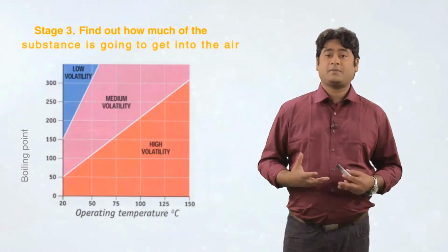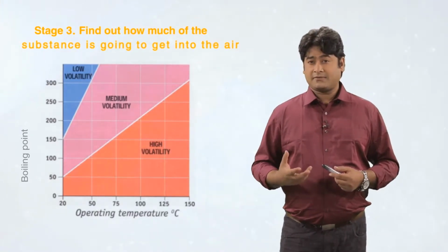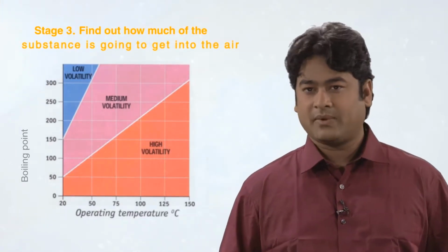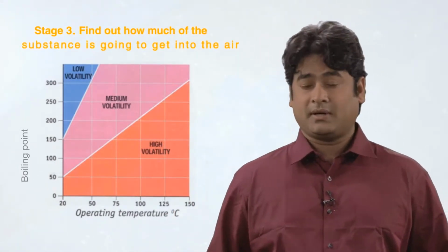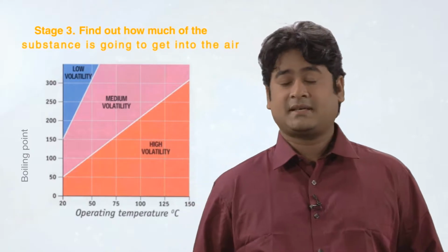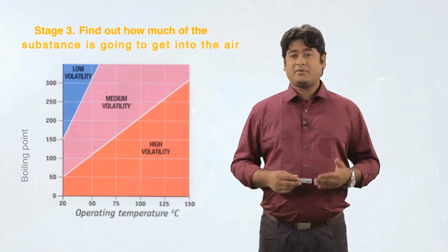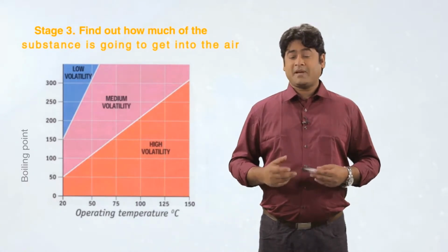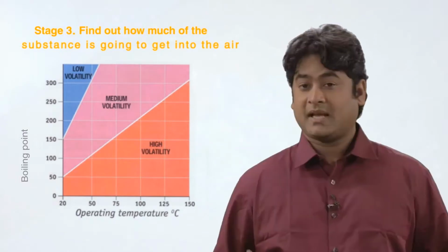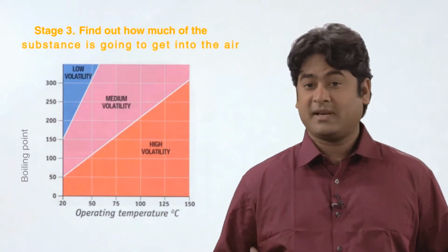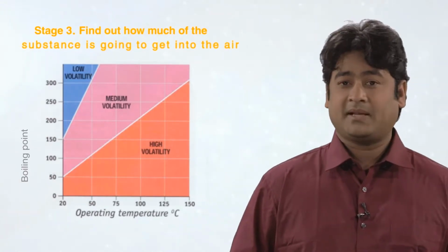If this chemical comes in a crystalline or granular size, there is a chance of creation of dust, but it will settle down very quickly. So in this case, the exposure will be comparatively lower, so the dustiness will be medium. Now if the chemical is in fine powder form, then there is a big possibility that a dust cloud may form during the usage, and it will definitely not settle down very quickly. So in this case, the dustiness of this particular chemical will be very high.